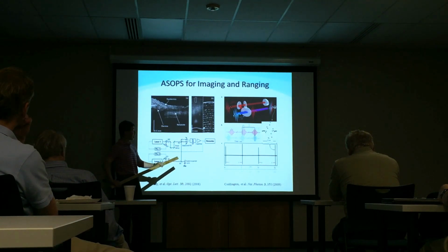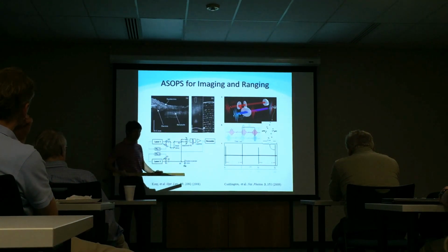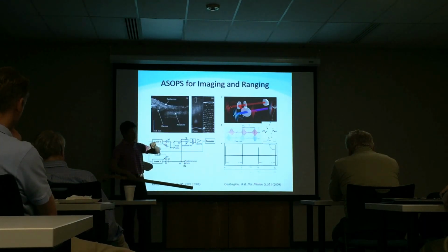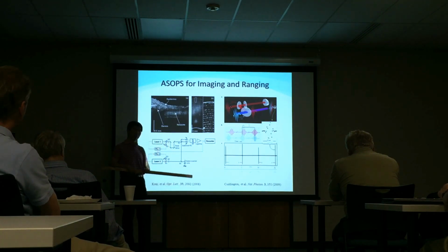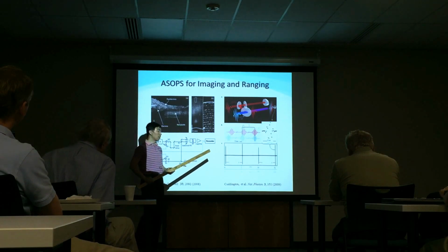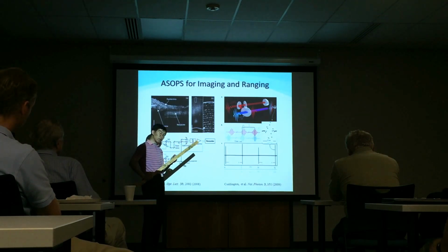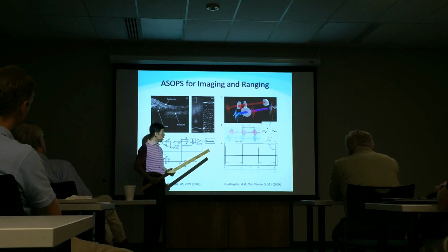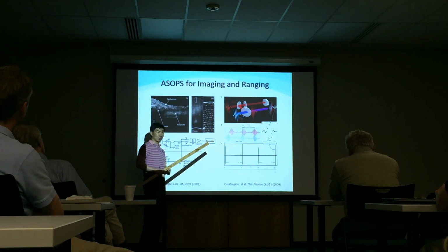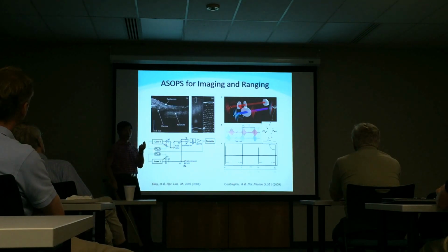And the nice thing about using the femtosecond laser is you can combine the time of flight method with these pulses. You can basically send a pulse and measure the timing of the pulse arrival time, and that will allow you to measure very long distance. On the other hand, you can interfere these pulses and create an interference method that will allow you to reach very high resolution.